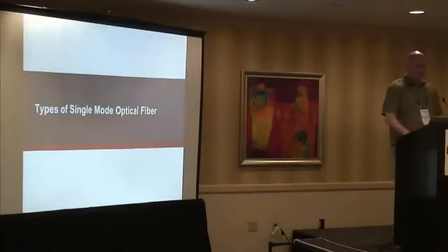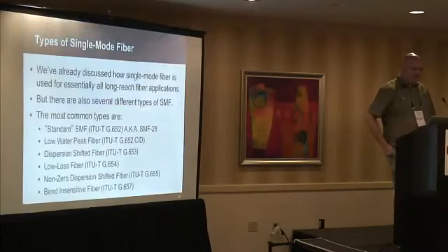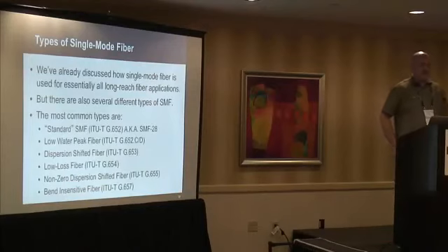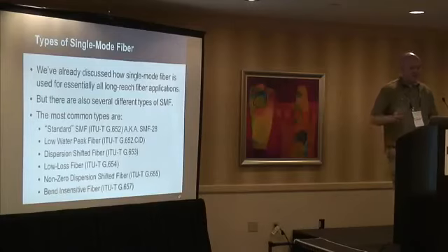So there's actually a bunch of different types of single mode optical fiber that we talk about. We already discussed that single mode is used for anything that's long reach, but there are all the different types out there. You've got your standard SMF, your classic SMF, which is called SMF28. You've got your low water peak fiber, dispersion shifted fiber, low loss fiber, non-zero dispersion shifted fiber, bend insensitive fiber, and we'll talk about a lot of these.